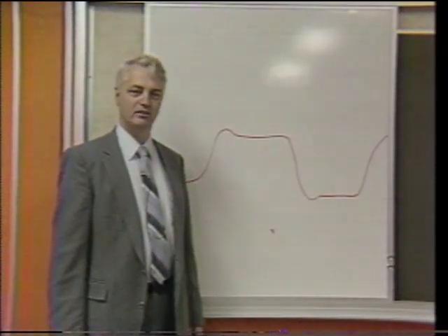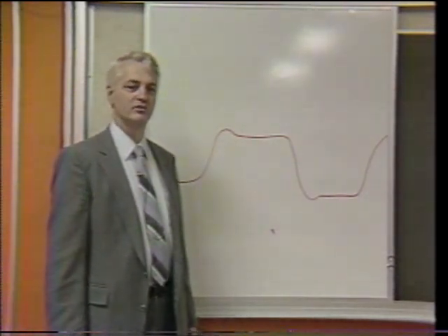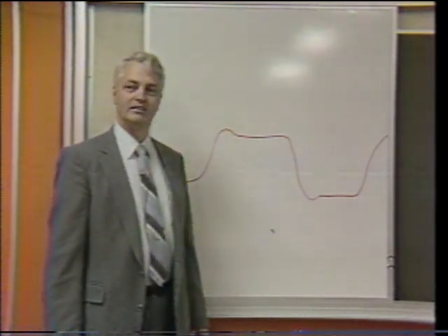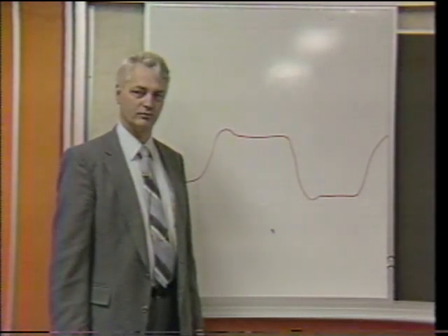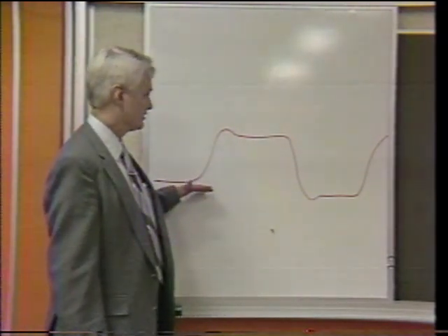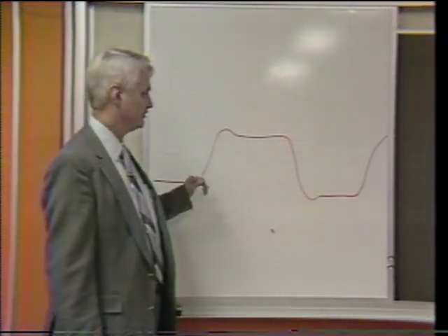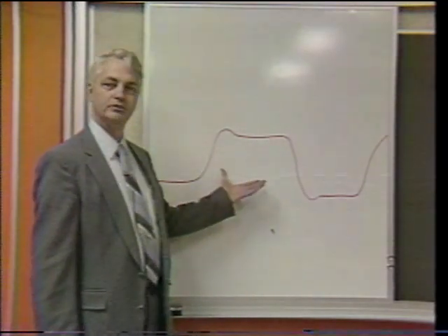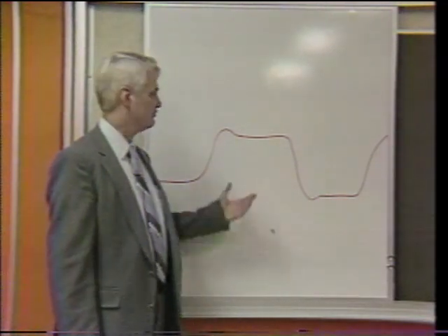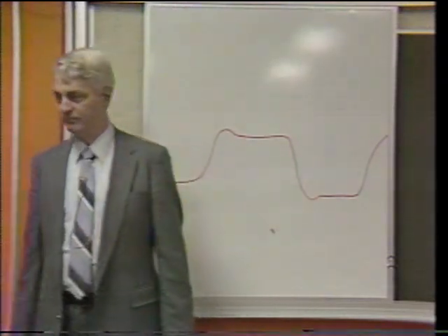What we're going to demonstrate now is some pulse measurements. Pulse measurements are very common in digital systems, data communication systems, because pulses are what define the characteristics of those systems. In order to understand these systems, we often want to look at things like pulse amplitudes, absolute levels of these pulses with respect to ground, how wide are the pulses, what kind of rise times do we have, what kind of duty factors do we have. So we'll show you those measurements on the 2465.